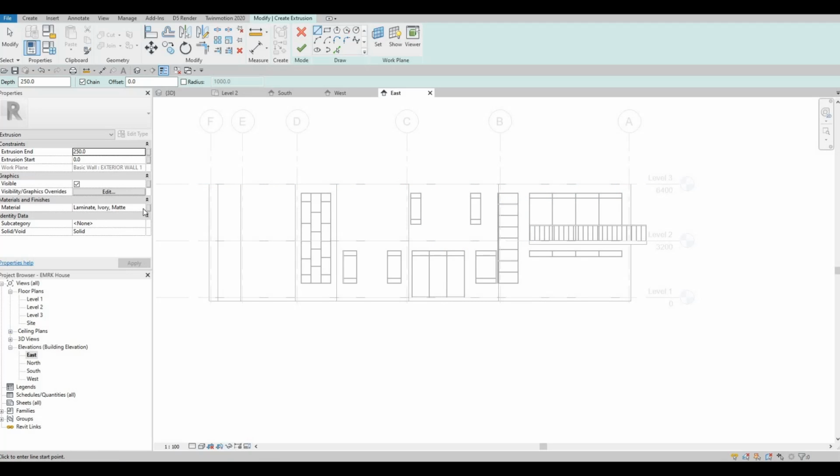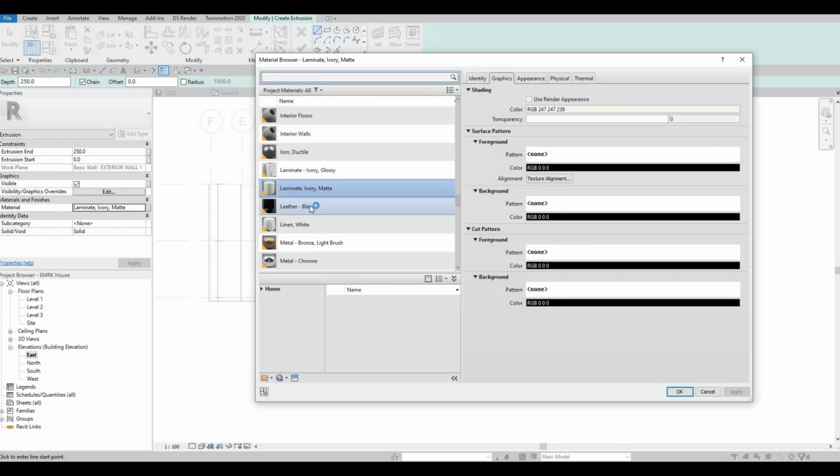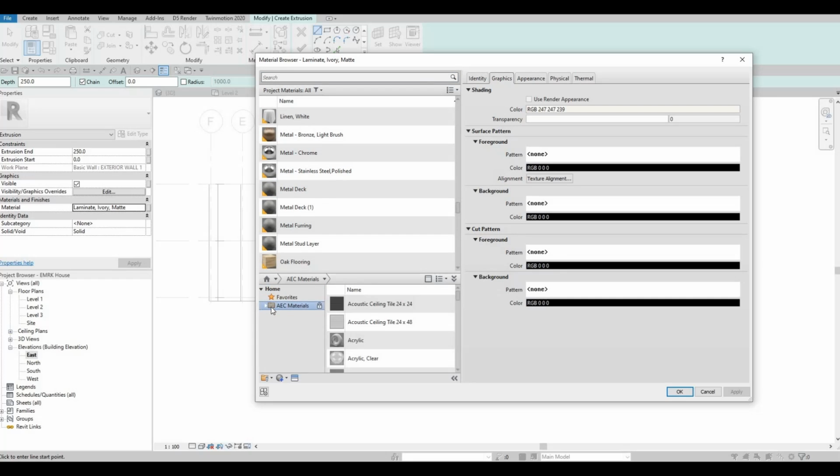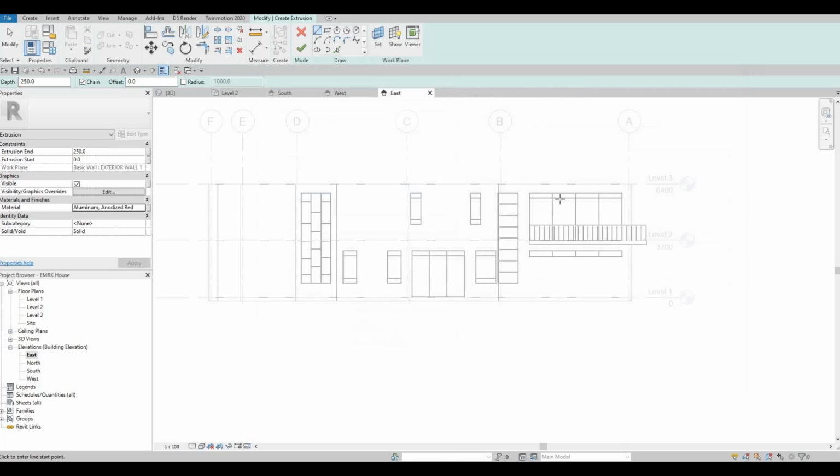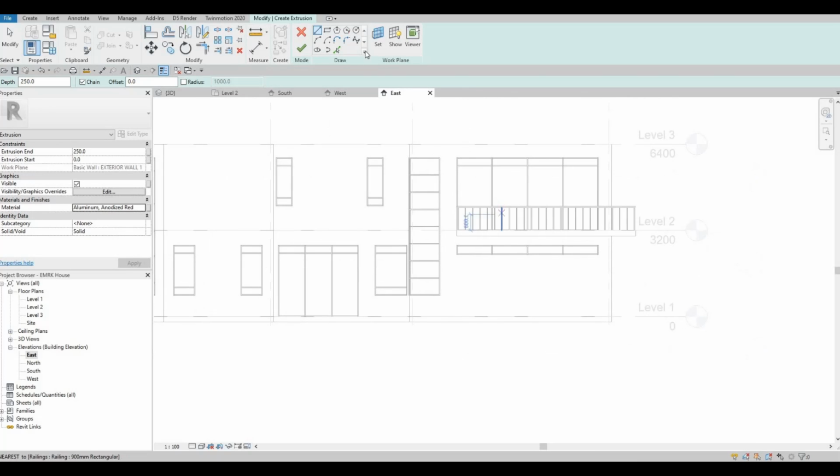And then now I'm gonna change the material so that I could change it in Twinmotion. So just random materials. You can go here at home, AEC materials, and as you can see, there's more here. You can even pull it down so that there's more categories. But here I'm just gonna pull up something different. I'm gonna pull up this, so just a random material.